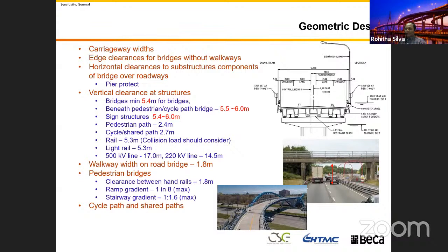So before you start the bridge design, that is the whole idea of this slide, make sure that your highway designer is happy with your bridge dimensions, because without your width and the vertical and horizontal alignment of the bridge, you can't design it. You need to make sure your highway designer is happy with what you're going to design also. Both of you have to work together with some understanding. Otherwise, if it is changed later on, you have to go back and redo your models, and you will see later on it's a lot of work.